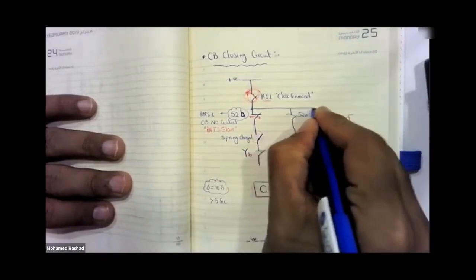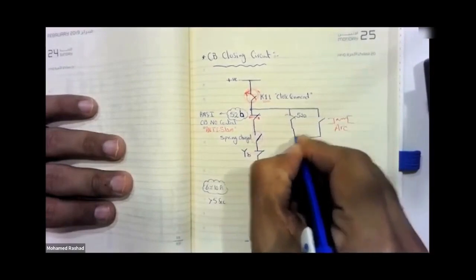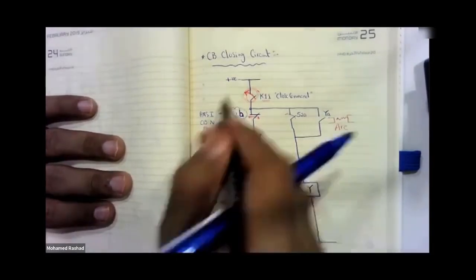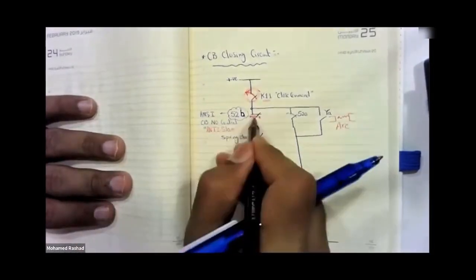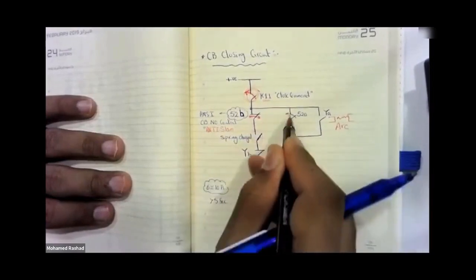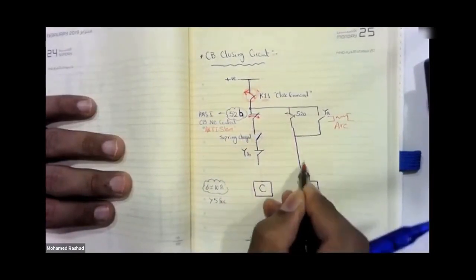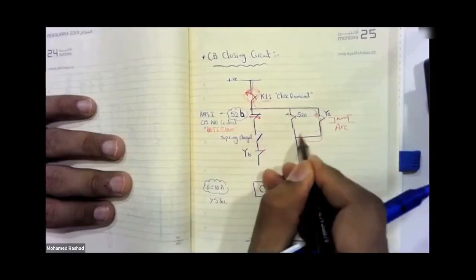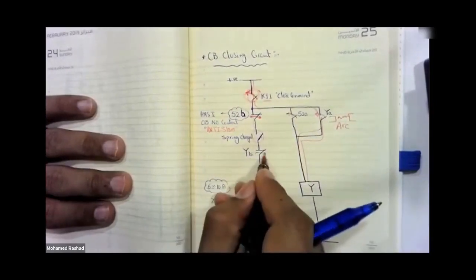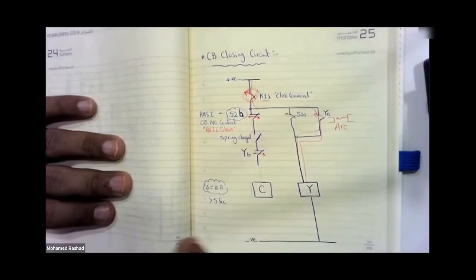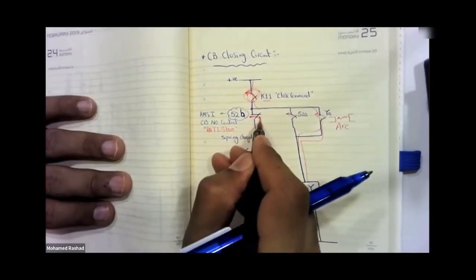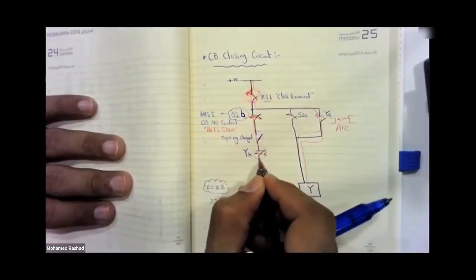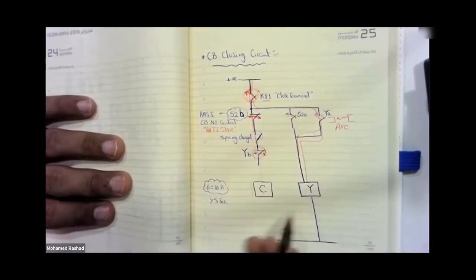That's why the component called Y, I will use it to self-latch itself. So how will the process go? Let's focus. I gave the close command, the breaker closed, this one opened, and this one closed. When this one closed, it activated Y. As soon as Y was activated, it latched itself. It closed this, creating a latch on itself in this manner. So now its contact is open, meaning even if the breaker opens again, this contact returns to being closed like before. The positive will go down, down, down, and find this contact open in its path. This is what we call anti-pumping.